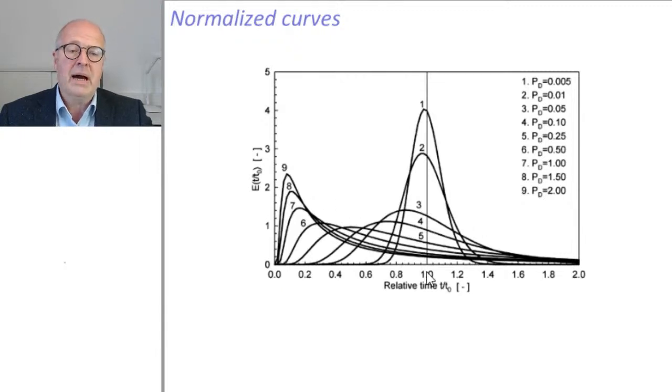So although we calculate and estimate a mean residence time of 7,000 years, it is possible the tracer shows up after 7 years, as shown in this example. This is just a property of the material that is fractured or heterogeneous and that has preferential flow. And here you see the theoretical concept behind this.